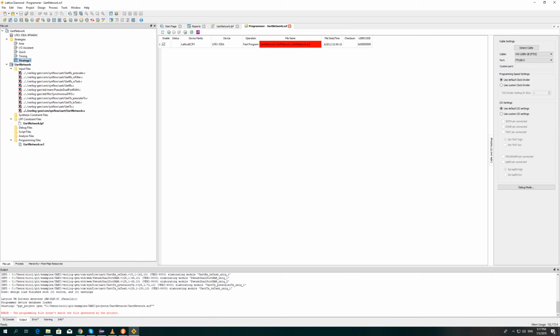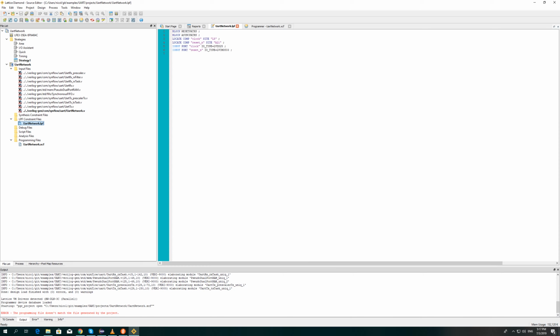So that's the next step. It's configuring the synthesis and adding the necessary options, necessary mapping. To do so, you need to read the documentation of your board provider or your FPGA to know the mapping of your own FPGA.